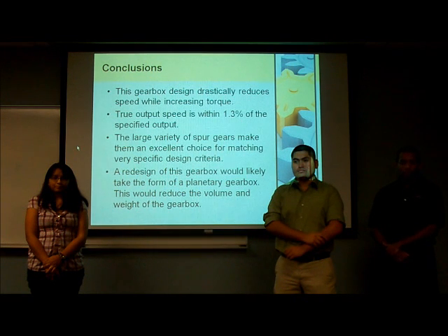Looking forward, if we were to redesign this gearbox, we'd probably consider using a planetary gearbox as opposed to a parallel shaft gearbox, and that would allow us to drastically reduce the weight and the overall volume of the gearbox while maintaining the robustness and the desired gear ratio.